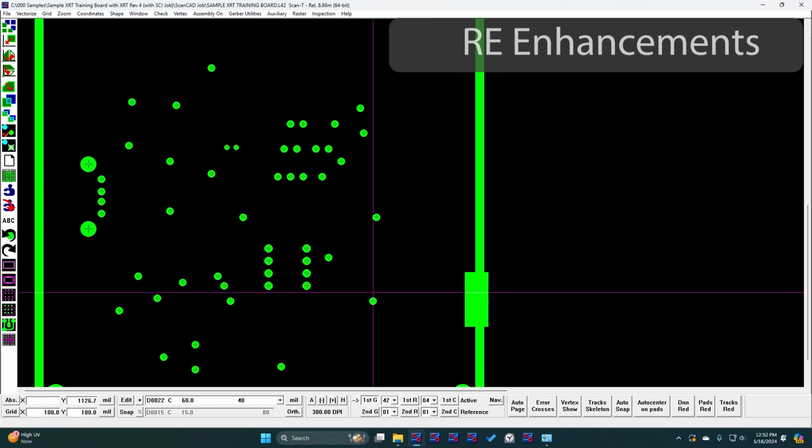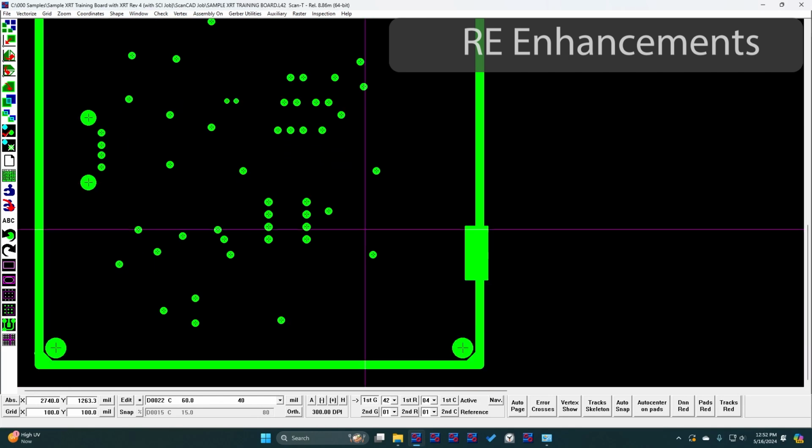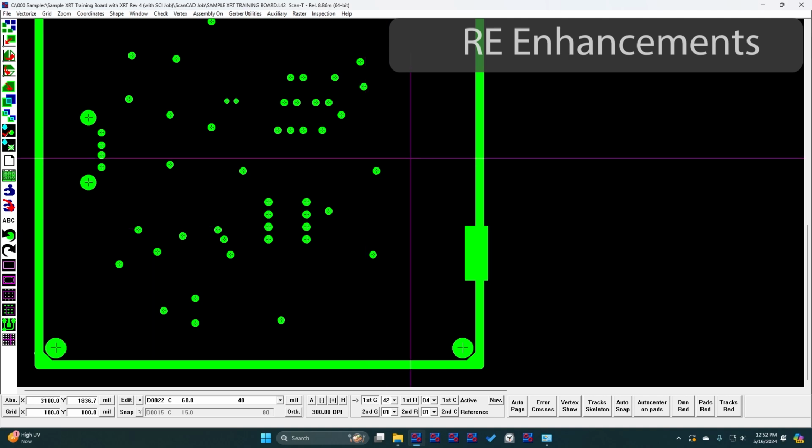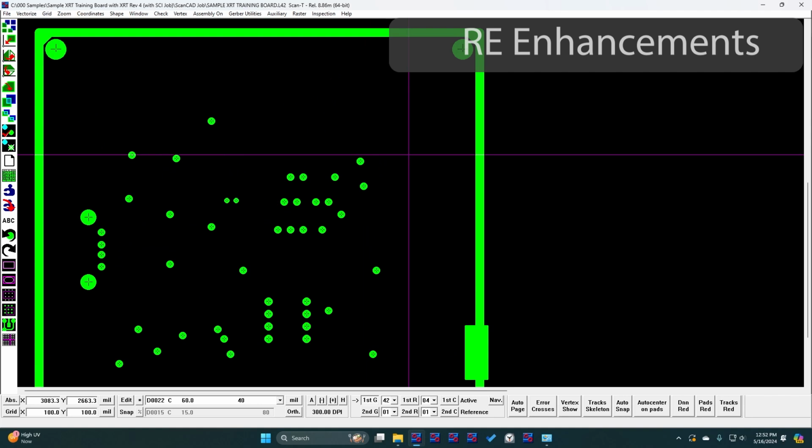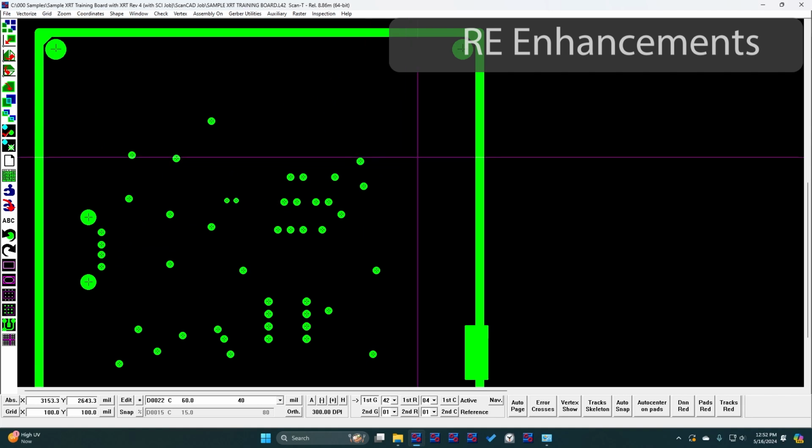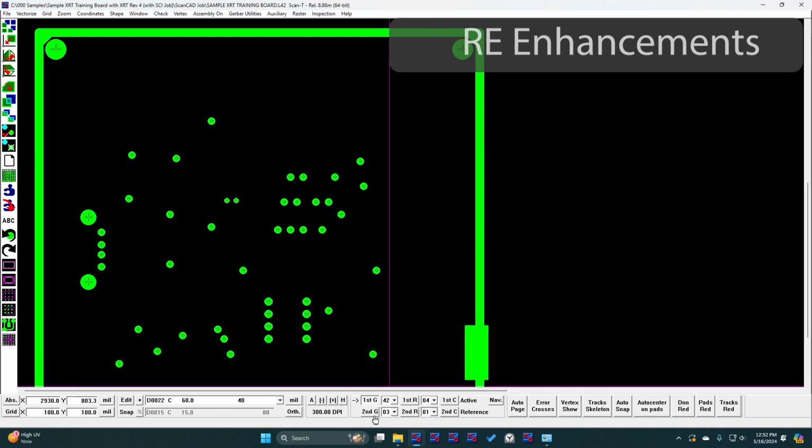And of course the reason why we do that is boards don't have great registration. The color image is not great, because the copper isn't great. And so you don't want to actually create the plane layer from the color image. You want to create it from something more perfect, which is your pad locations that you've already programmed. So we develop a mask like this, and then in the traditional method, we go through Convert Plus to create a fill layer.